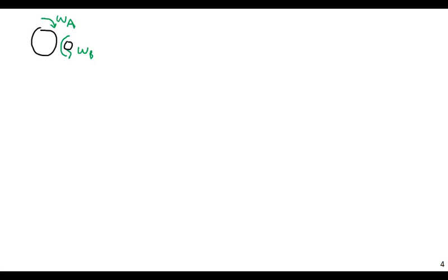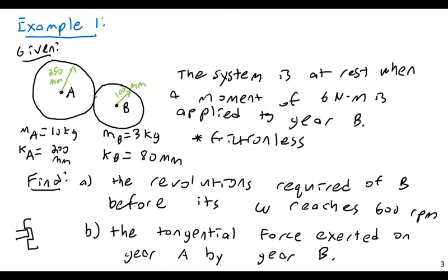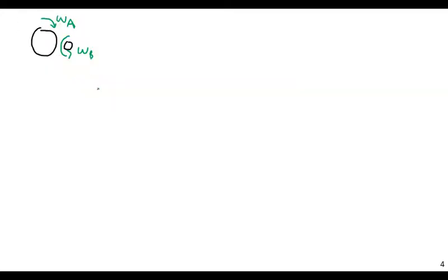These are two surfaces, and I didn't draw them right on top of each other, but as we can see here, these are two surfaces that are physically not going to slip past each other. They're not bearing on via friction or something like that. What's going to keep them rotating together is their teeth, not bearing friction. I just didn't feel like drawing them like full gears. But in reality, they have teeth that are intersecting and preventing them from slipping past. So this plane must move with this plane here. They're not going to have the same angular velocity, but they will have the same tangential velocity.